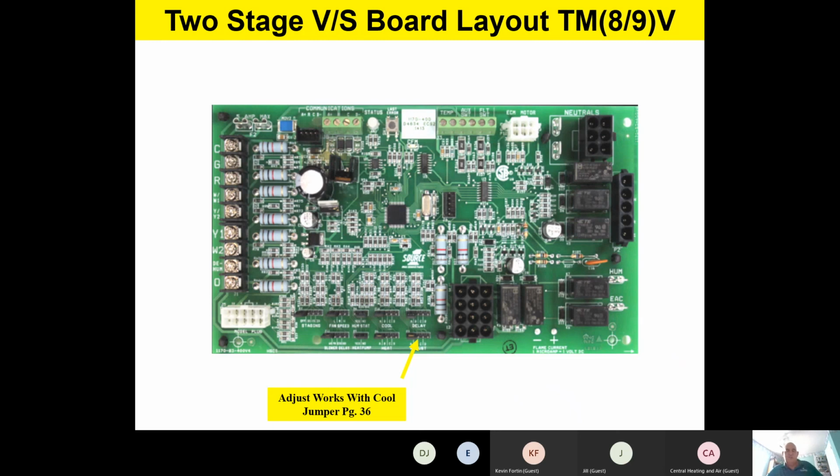Please remember the cool and the adjust jumpers work together to set up or to program your cooling airflow. Now, please write this down, everyone. You're going to set up this board based on the tonnage of the outdoor unit.